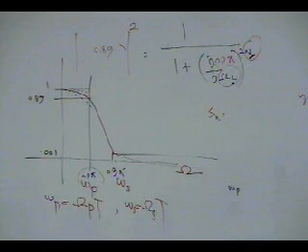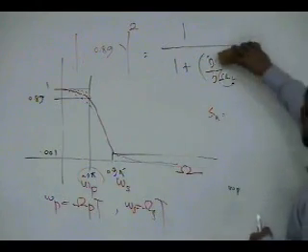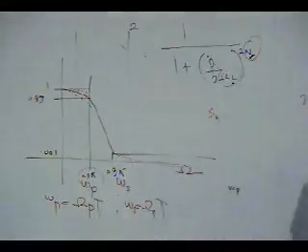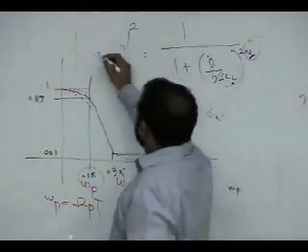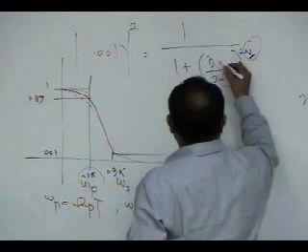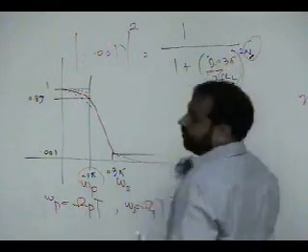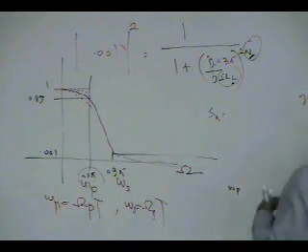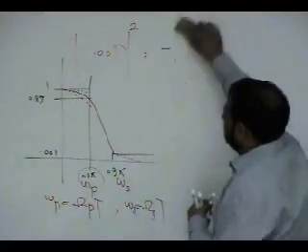How do you get the other equation, the second equation? It is at 0.3, 0.001. So it is 0.001 and here is 0.3 pi. If you do this, you have two equations, two unknowns. Solve the two equations, find out n and omega c. You know n and omega c, you go plot all the poles, you know all the poles in the z domain, so you have solved the design problem.